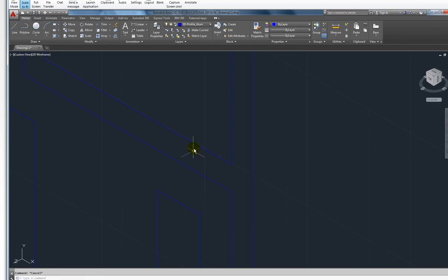Why is that aluminum piece so complicated? Because aluminum is not that strong, so to make them strong they add a lot of bends. The more bends you add, the more strength it gives, because it's thin. Also, there are thermal breaks. The aluminum outside typically doesn't want to touch the aluminum on the inside, so they're separated by gasketing. Otherwise the cold comes right in. It conducts right in. So there are thermal breaks. That looks like a joint. So that's why. I think I have that all set up.